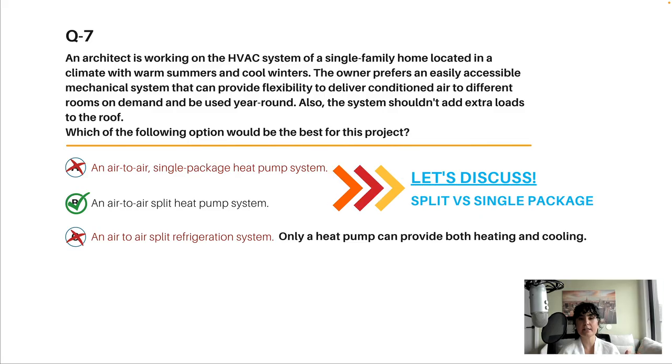And the question says the system should not add extra loads to the roof. As I explained here, the single package heat pumps are usually placed on the rooftop, so that's extra load. So the client doesn't want that. That's why we picked split heat pump systems as the best option in this question.